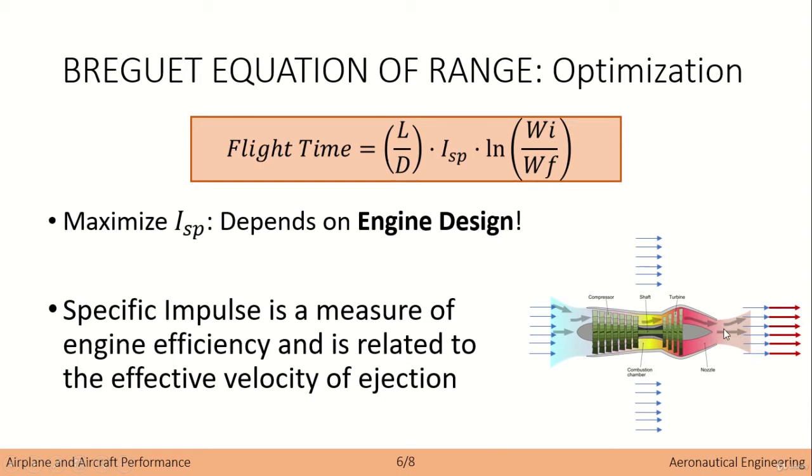through the engine, okay? So basically we have the total aircraft, which is traveling at a certain speed. So we have a relative speed between the wind and the engine, which would be this speed over here. And because we have the engine and we get thrust from the engine, the exhaust velocity, which means the velocity at which the air or the wind is getting out of the engine, is bigger than the relative velocity of the wind with respect to the engine, okay?